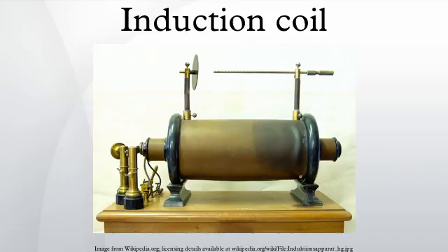described above, these were inadequate for powering the large induction coils used in spark gap radio transmitters and X-ray machines around the turn of the 20th century. In powerful coils the high primary current created arcs at the interrupter contacts which quickly destroyed the contacts. Also, since each break produces a pulse of voltage from the coil, the more breaks per second the greater the power output. Hammer interrupters were not capable of interruption rates over 200 breaks per second, and the ones used on powerful coils were limited to 20–40 breaks per second.